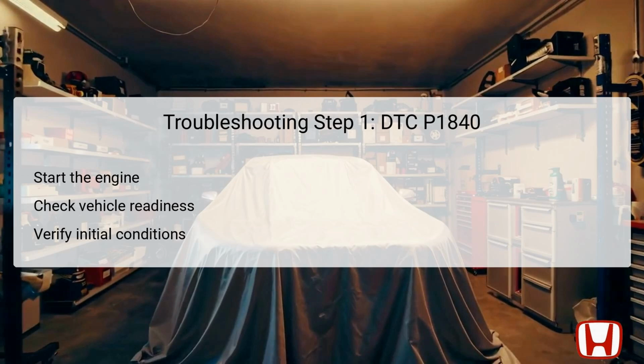Checking for readiness includes confirming that no other diagnostic trouble codes, DTCs, are present that might interfere with the tests for DTC P1840. Following these initial checks sets the stage for more detailed diagnostic evaluations.